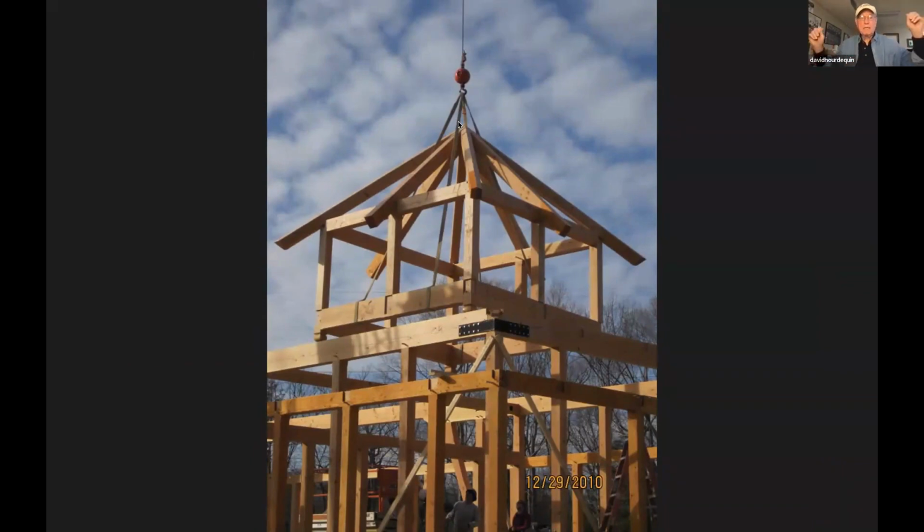what am I trying to say? Won't come to me. Anyway, yeah, just simple statics. You can determine what the compression is in this member, and it will have a horizontal and vertical component, and you put the horizontal component in, and there's your tension ring. The vertical component is taken care of by the post, and the bird's mouth, this member will have a notch in the bottom of it. And of course, to hold this member to the tension ring, you have to screw it down into it to resist the forces that want it to slide outward.